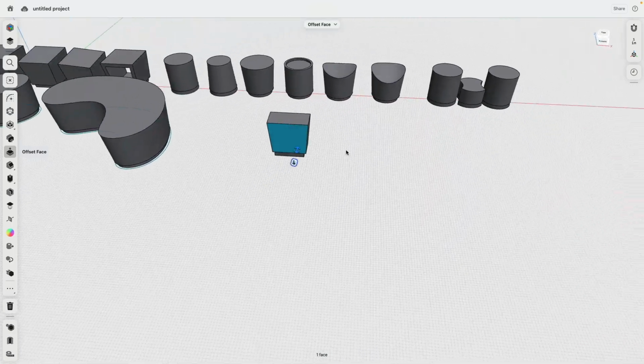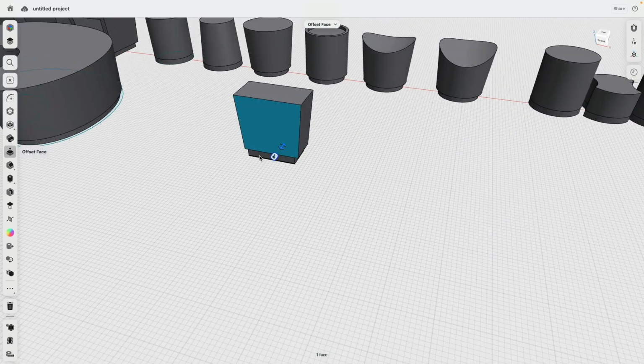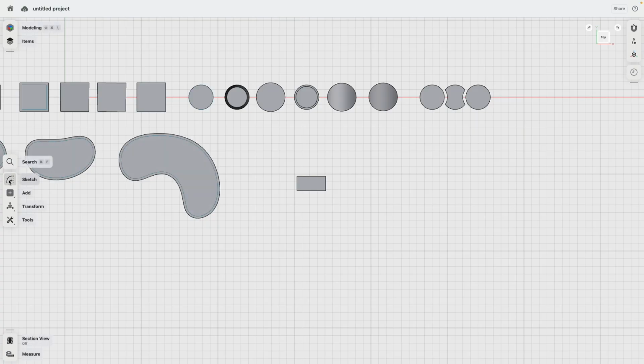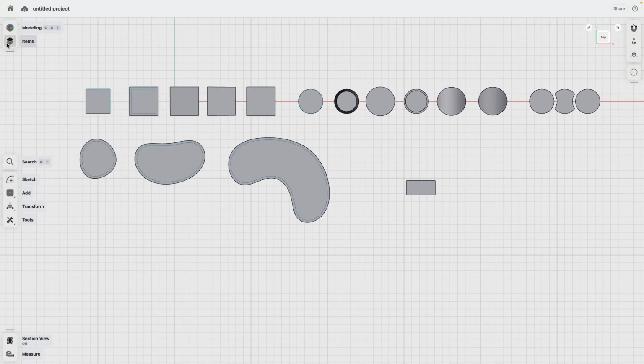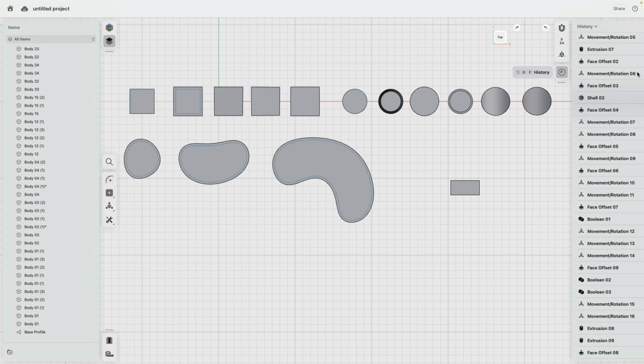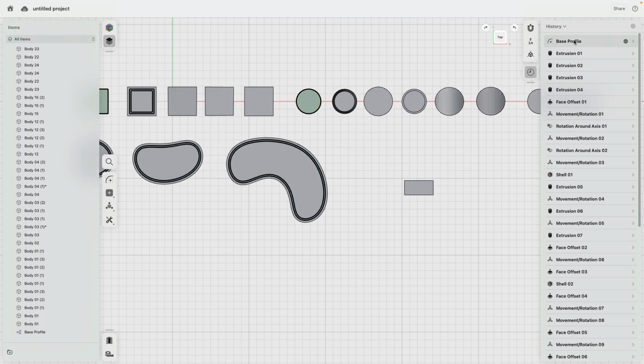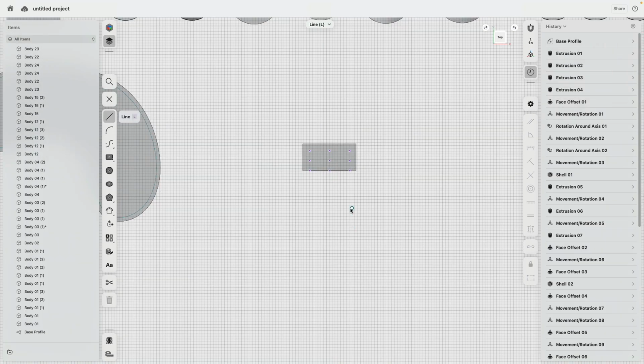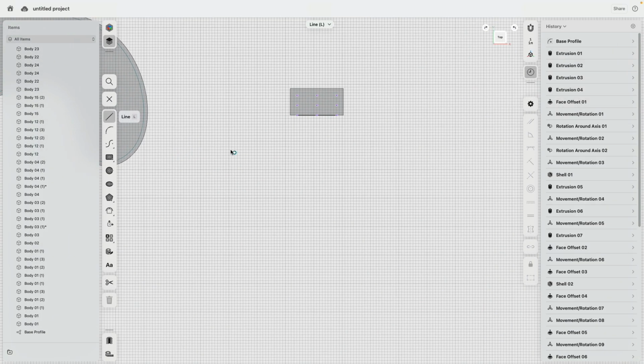So now we actually have a profile as a sketch. Instead, I could have drawn this, or I simply use the geometry and make a section cut and use that to create my sketch. This time, because this is a modeling step that happened at the end, and I made the sketch at the beginning, I should now make a new sketch, because I can connect this sketch now to this piece of geometry.